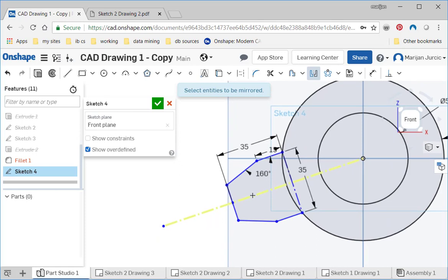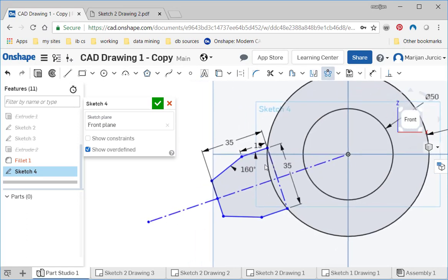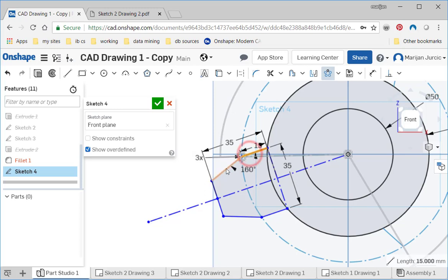Okay, we're almost there. Next thing is I want to revolve or polar array this around. I want 6 of these, right? So there's a polar array right here, or here they call a circular pattern, good. So now I need to select all the pieces that I want to go around. So 1, 2, 3, 4, 5, and 6.